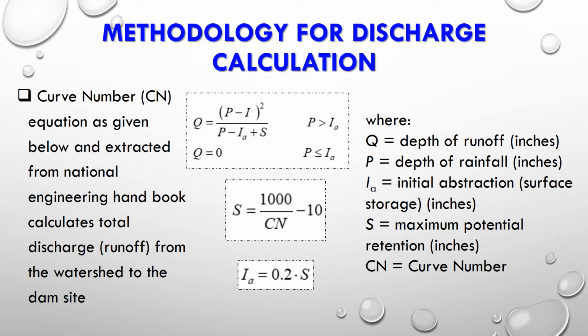And the P raster, that's the depth of rainfall raster, will be created using the precipitation values downloaded from the USDA NRCS Geospatial Data Gateway, which is created through the PRISM program, PRISM being an acronym. And at the end, Q, the entire runoff amount or discharge amount from the entire watershed, will be created as a raster using the equation shown in the middle.